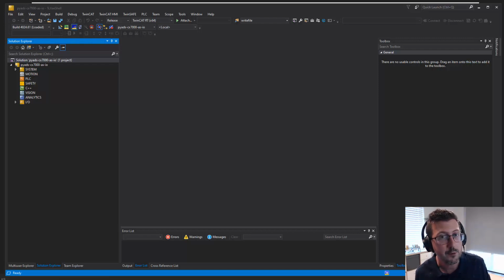Now that's completely possible. Obviously we've got things like bus couplers where we support multiple protocols, for example, Modbus TCP. So if you have those libraries in your language and you can speak Modbus TCP, that's all possible. You can use one of the bus couplers for that, attach a whole host of I/O to it and interact with it that way. Now, the downside with bus couplers is they are typically limited in what terminals you can put on the side of them.